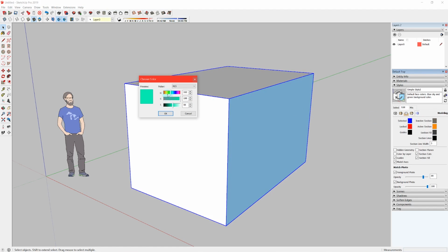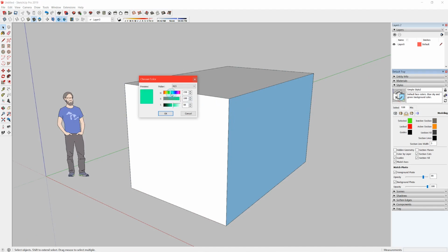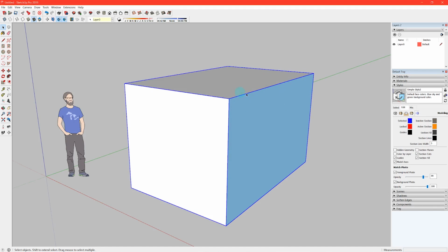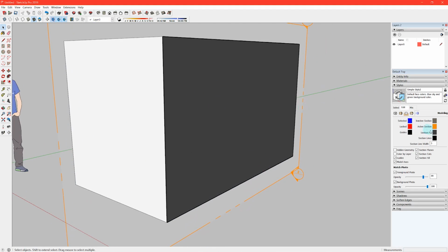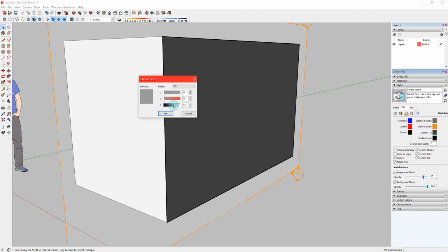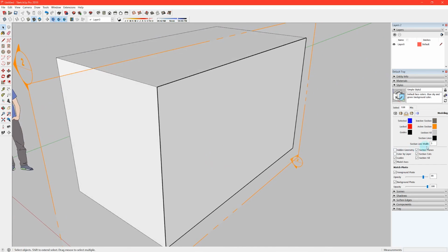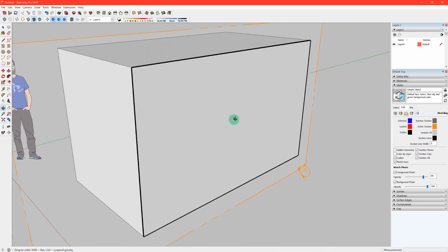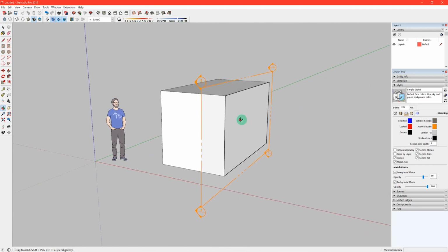And then you can go into further detail, and you can choose what color your selection box is. You can choose what color an object is if it's locked. But something I do like to change is the section fill. The default is a black, but it's hard to differentiate between the actual section cut lines and the cut itself. So I usually like to make it a lighter gray so that you get a better idea of where the actual section cut outline is. But once again, all this you can fiddle around with and get it to look exactly how you want.